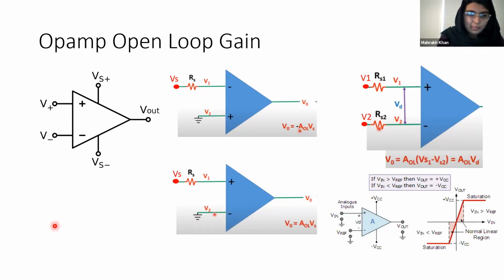So you remember that whenever we exceed this voltage, or decrease the voltage more than this voltage, it saturates. It does not give you a voltage greater than this. So if our input voltage exceeds, and you are providing 12 volts, it will just produce 12 volts.